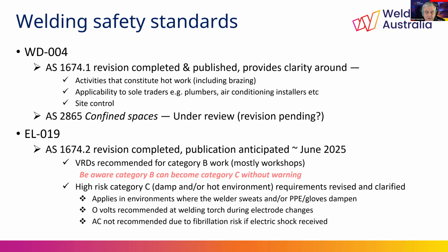Now, as with the previous edition and the 2025 edition of AS 1674 Part 1, it is imperative that a risk assessment is performed and appropriate fire precautions are taken and a hot work permit issued when required. Now, in the eyes of the insurer, failure to comply can mean that the insured has not identified the hazards and the required controls associated with hot work, and insurance cover can then be denied, placing the business at risk of insolvency in the event of a fire.